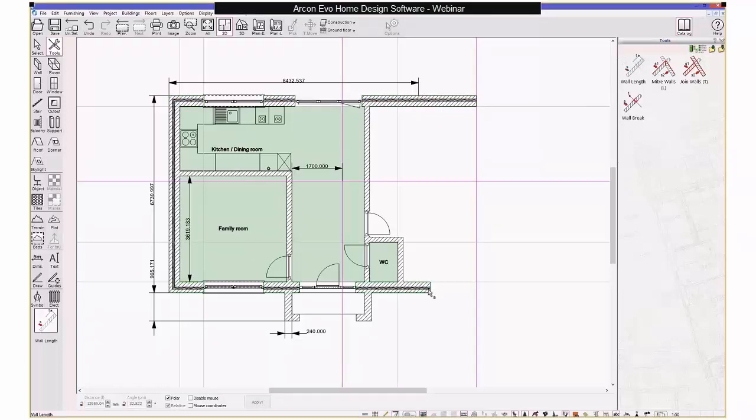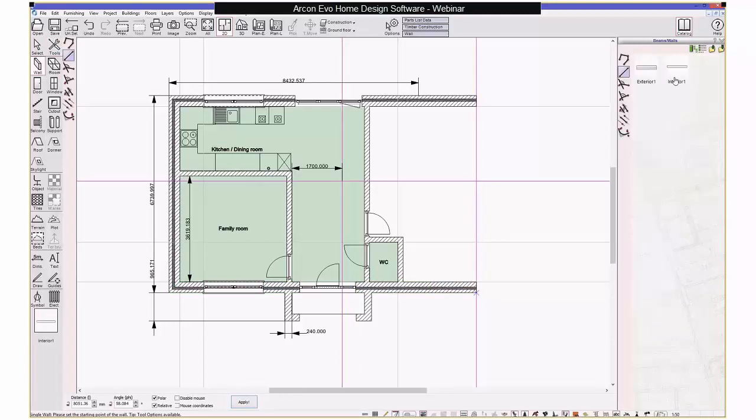external wall below, and then I'm going to click on the wall options here. I've just created a wall type earlier on. I'm just going to click on here and then place this wall in position. So as you can see here, I'm just using the guidelines to position the wall in place. There's a number of ways of planning out your drawing. You can use guidelines or helplines to peg out where you're going to draw the walls, and that's my preferred method, using guidelines.